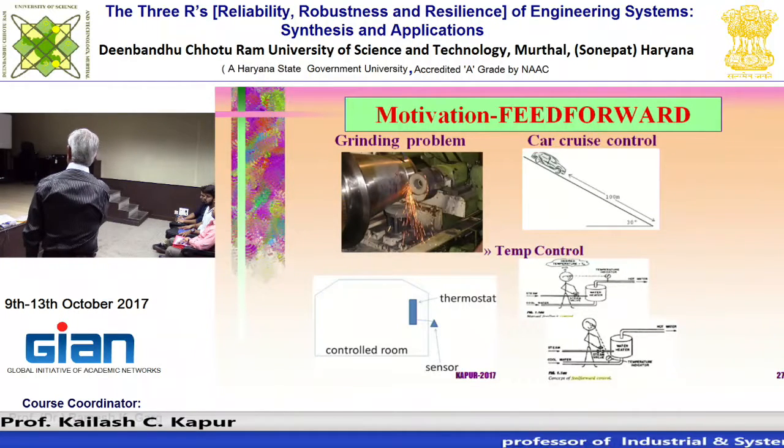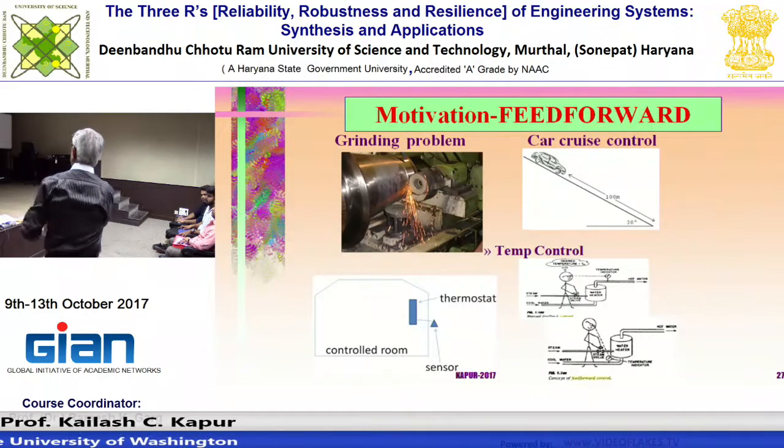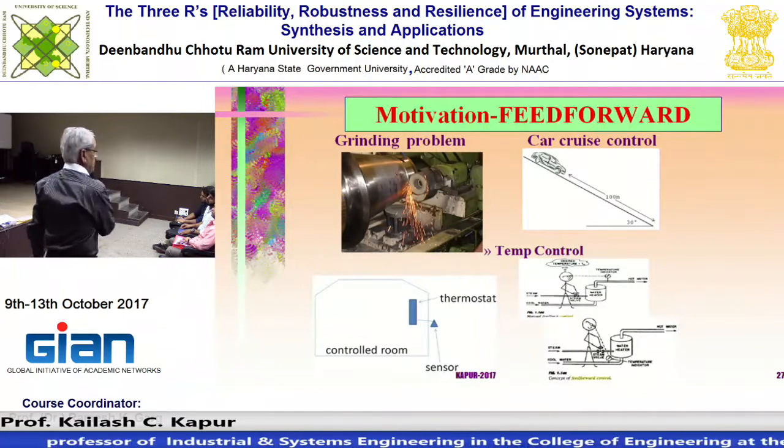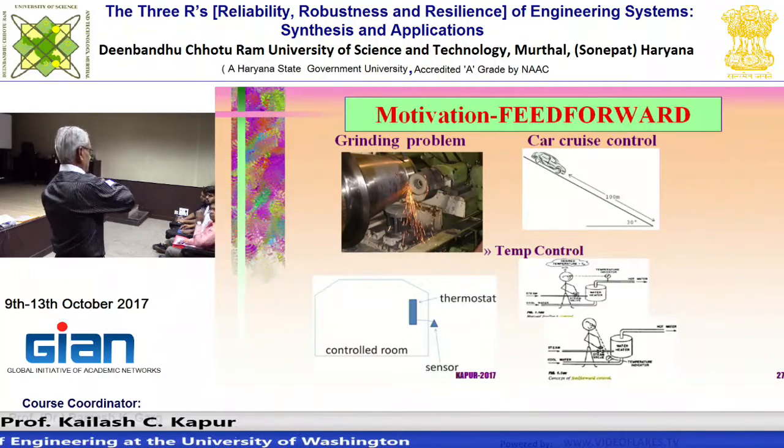And as the temperature changes, they could change the water flow so that the water temperature becomes at target. So here you can see eyes are on the outlet, but this is bad because you are already going to have water that is not at target. And then you're going to change the input.